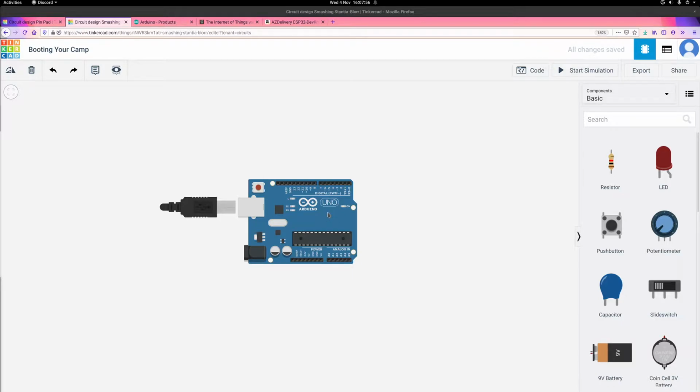But this here is an Arduino Uno board. This is one of the most popular starter ones, I would reckon, though there are bigger ones, smaller ones for different purposes. But the basic layout of the board is this chunk here is where the actual microcontroller itself is. On a real board, this is something that you can pull out and slot in a new one. So if for some reason your chip breaks, for example if you manage to hook something up wrong and fry it, you can get a new one, just slot it in. So that's the brain of the board, if you will.